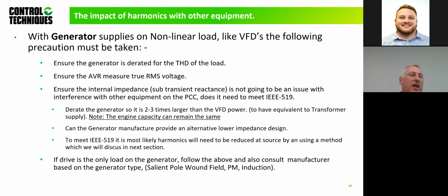And of course, in our existing diagram, we have a connection at low voltage, and we've got 2 to 3 times higher transformer impedance. So the generator is going to struggle. Yeah. Just basically on that subtransient reactance. Of course, we've got a 1 MVA generator. It's a lot larger than our load, we hope, based on the other point of common coupling devices.